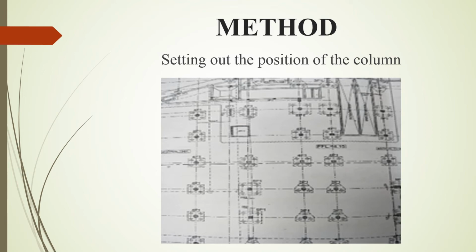Setting out the position of the column. The position of the column will be set by the surveyor before the concrete work of the footing is done. Normally, the position for every column of the building foundation is aligned by the design grid line from the consultant.